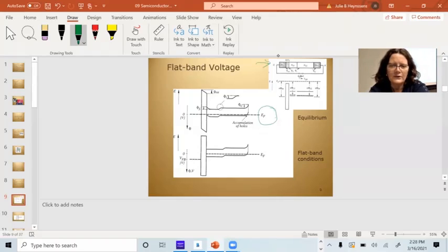So what I see here, I see this big barrier right where I have the oxide. And on the other side, I have the metal. And inside the semiconductor, I've got one region of doping and another region of doping here. And I can see that the bands bend a little bit. Now the goal is to turn this transistor on. I've got to put enough energy on this side to accumulate charge on this side to make the bands flatten out. We call this the flat band condition.